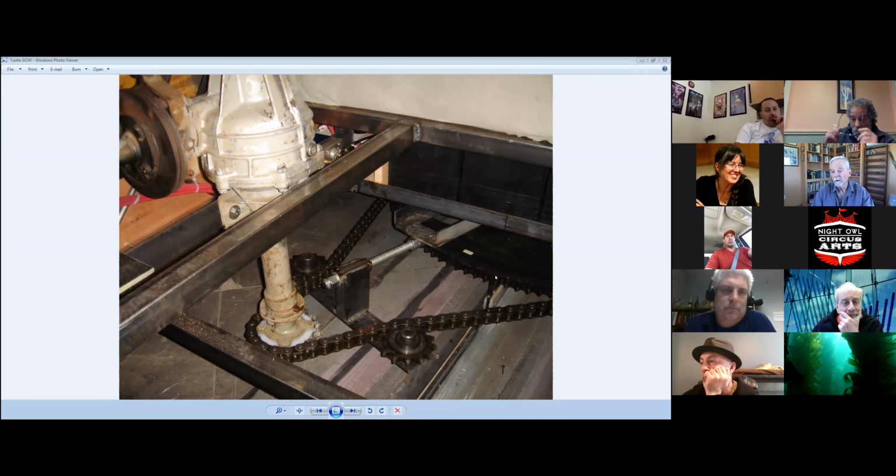This drags the sprocket up and down stage, and the truck follows because the truck is sitting on top of this. We got an old surplus golf cart differential, turned it on its side, locked one axle, and set it up so that this sprocket would drive the bigger sprocket. We had the regular DC golf cart motor and controller, so that when the driver put his foot on the gas, it would actually rotate. If you change the gear shift, it rotates in a different direction. This whole thing could move.